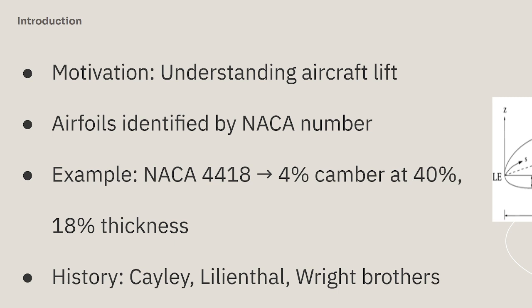My motivation for this project came from a long curiosity of how something as heavy as an airplane can stay in the air for a long period of time. To understand that, I studied how airfoil shape affects lift and drag. Airfoils are labeled using the NACA system. For example, the NACA 4418 means 4% camber located 40% from the leading edge and 18% thickness. The idea of using airfoils dates back to early aerodynamic pioneers like Cayley, Lilienthal, and the Wright brothers, who laid the groundwork for modern flight we see today.